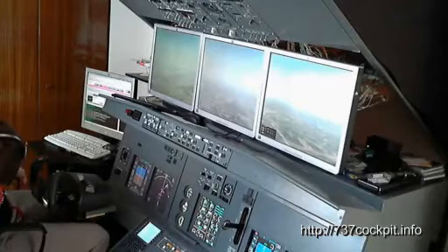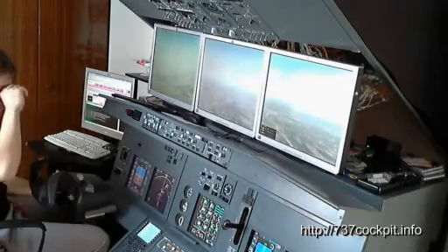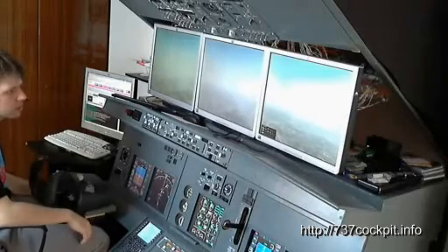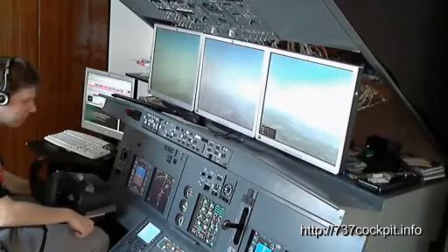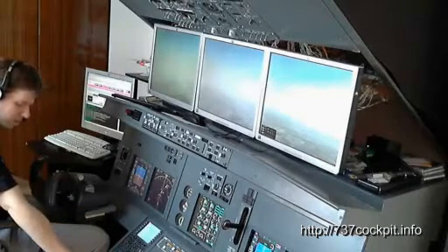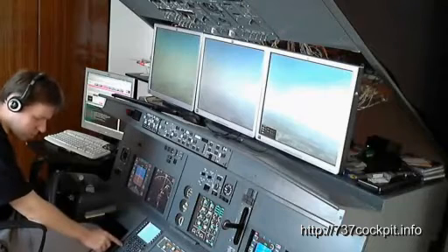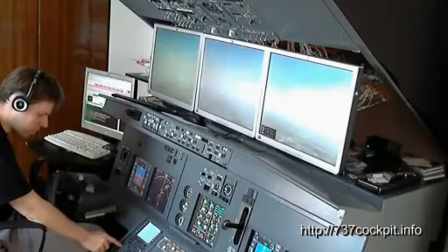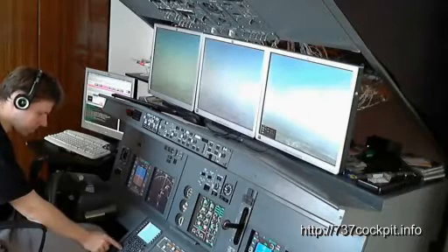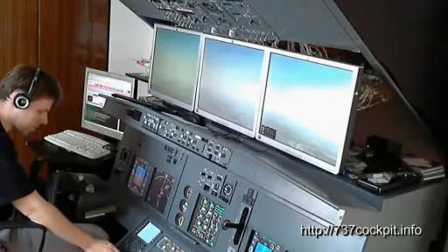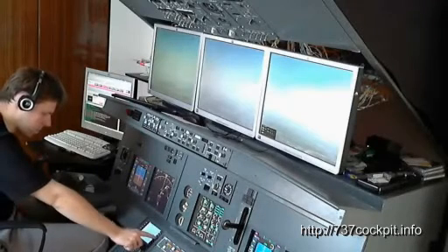And after passing Sierra Tango Echo, we will change it to Whiskey Oscar. Whiskey Oscar will be then, in case of any missed approach, our breakout point to the right, direct to Sollenau. That means we will enter Sollenau frequency 115.5 from our NAV 1. We had it before on the NAV 1, now moved to NAV 2.